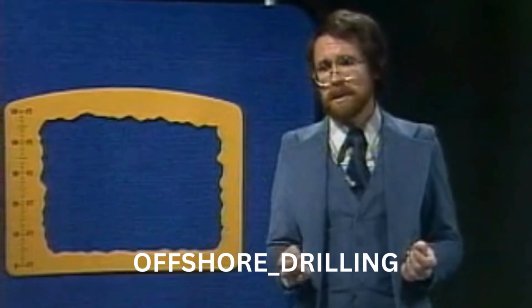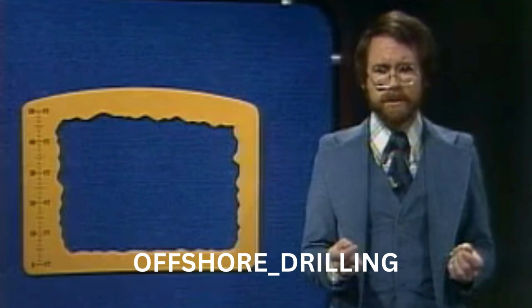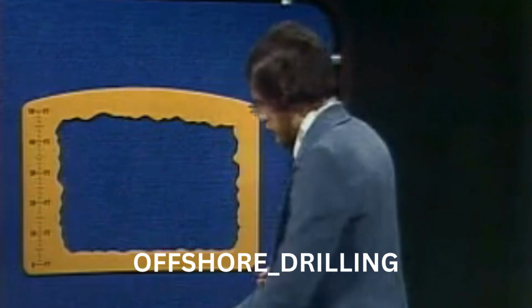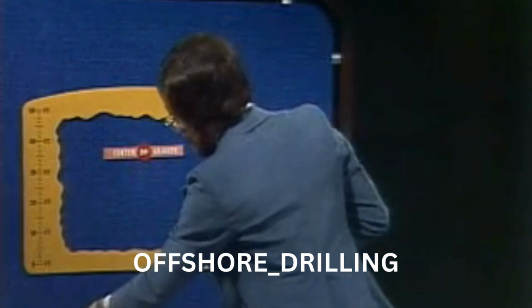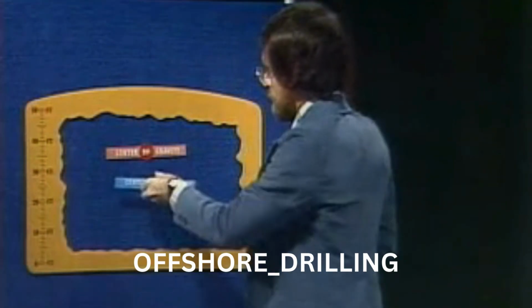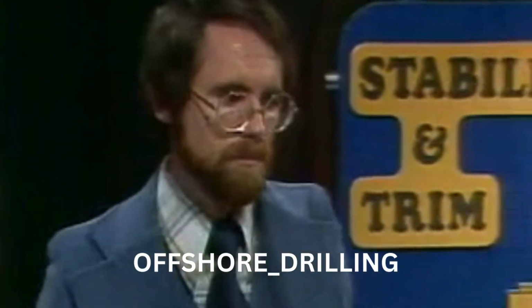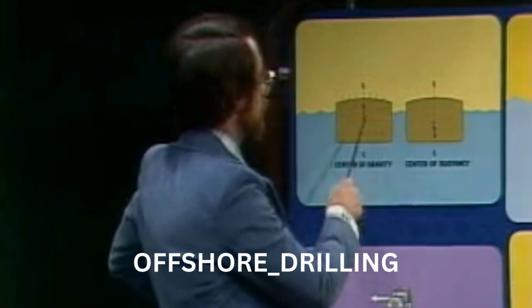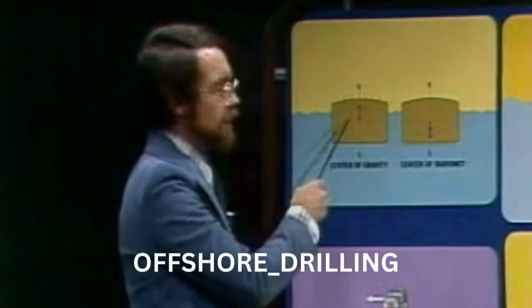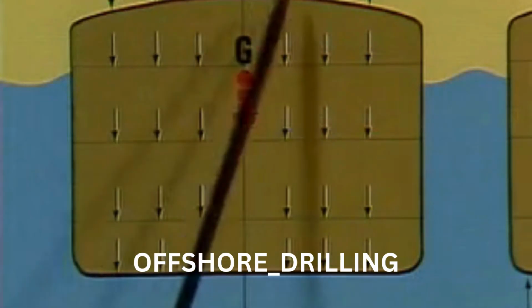We can determine the stability of a vessel by locating 2 points in the vessel: the center of gravity and the center of buoyancy. The center of gravity, what we will call G, is the center of mass of the vessel. It is at that point that all of the vertically downward forces of weight seem to act.